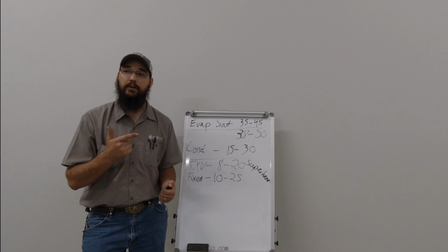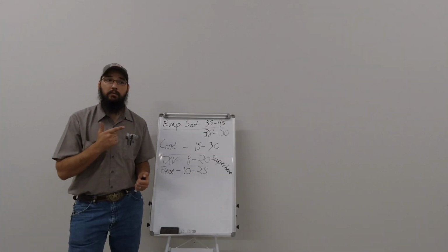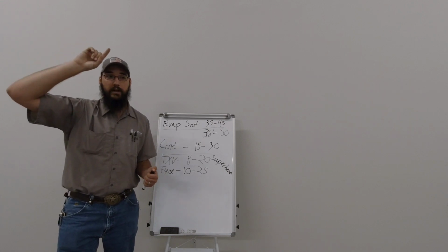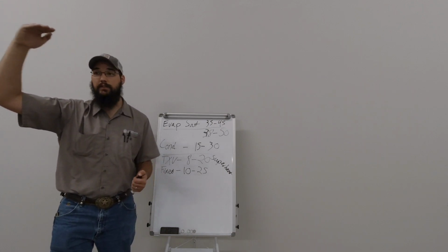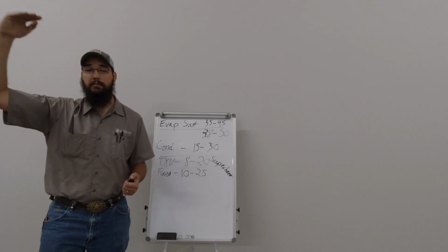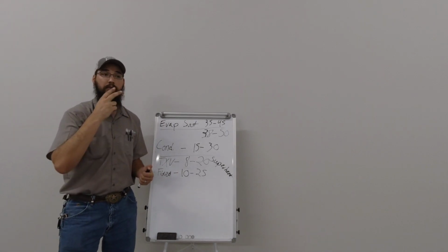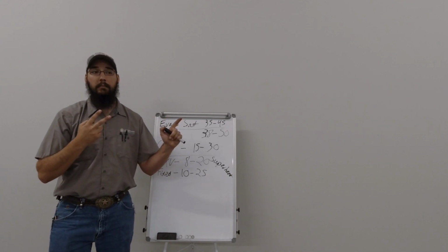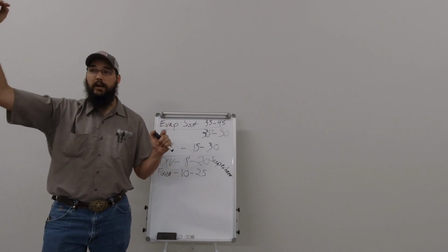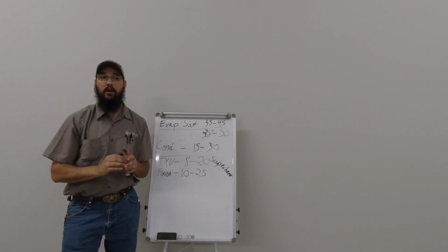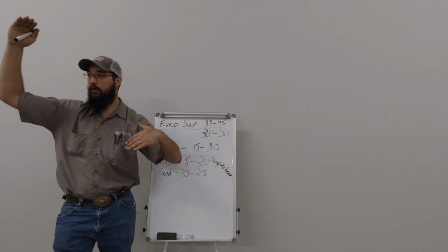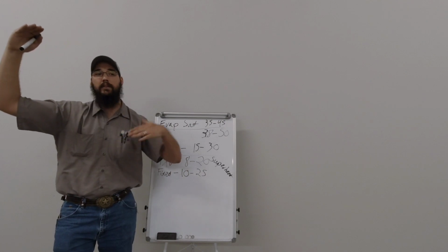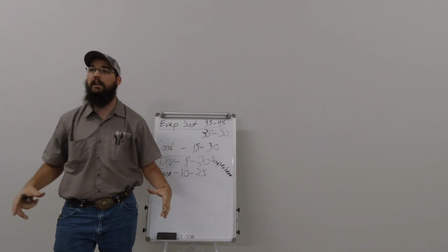With both compressors together, my expectation is now that the one compressor, which is going to have a really high saturation, right? One compressor by itself, saturation is probably going to be in the 50s minimum, somewhere in the mid to upper 50s. I bring on compressor 1 of circuit 2, run it together. My expectation is that superheat and saturation are going to come down, because now you've got this large coil that's made for 4 compressors. Instead of one compressor trying to run that whole 75 degree load by itself, you've got 2 sharing the load, splitting the heat on that coil.